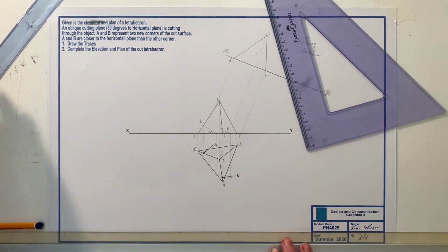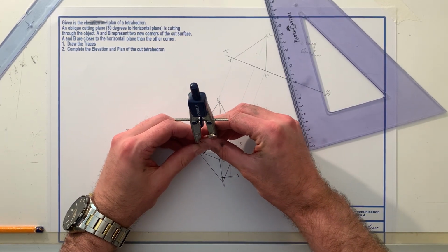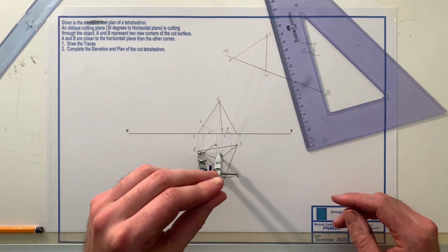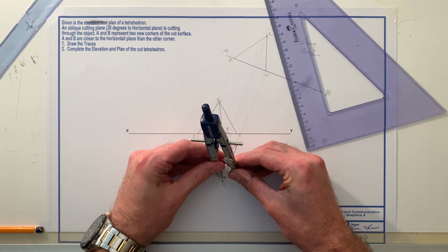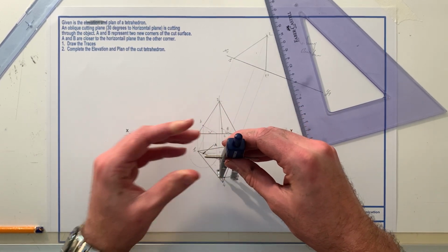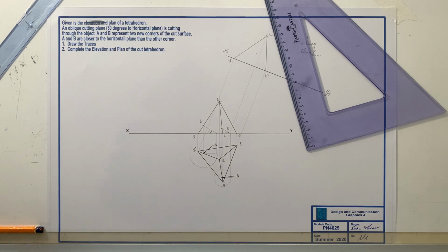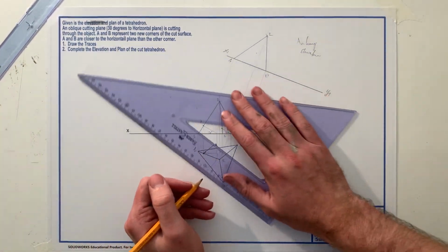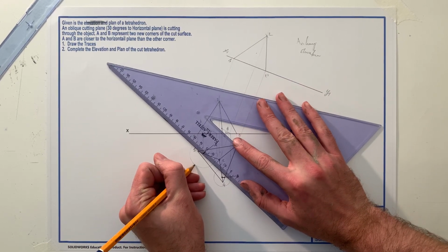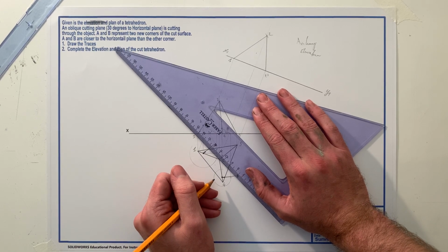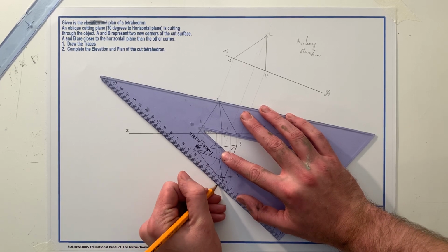And then I have to construct my base circle. I only need to construct a portion of it, just to find where I can draw a tangential line to the two of them. Like so. And my second one. Like so. Now I can line up a straight edge against these two curves. You can use a construction to find out how to draw a tangent to two circles, but for this I won't be too worried about it, just line up your straight edge the best you can.